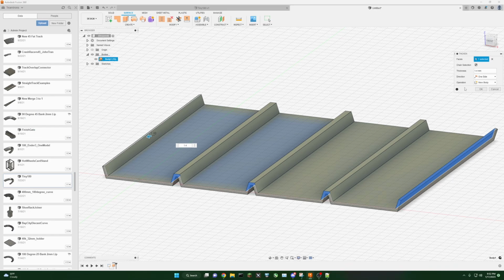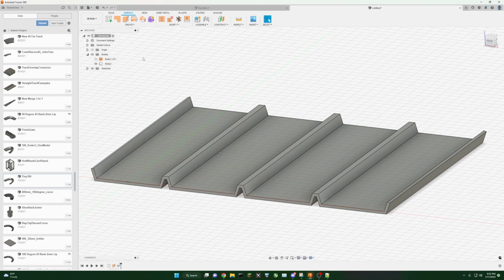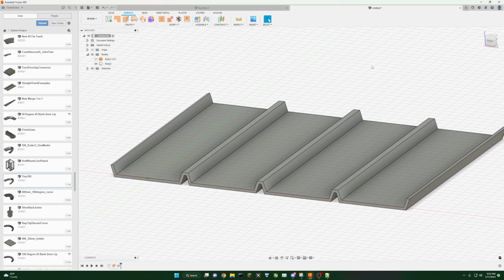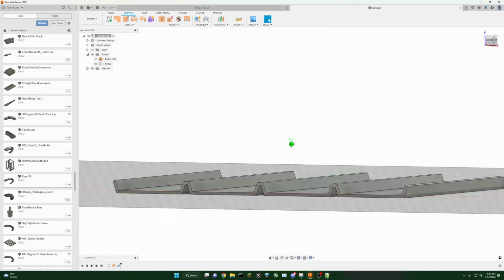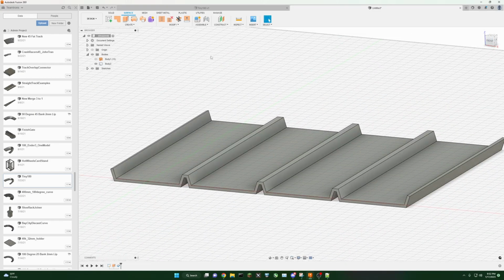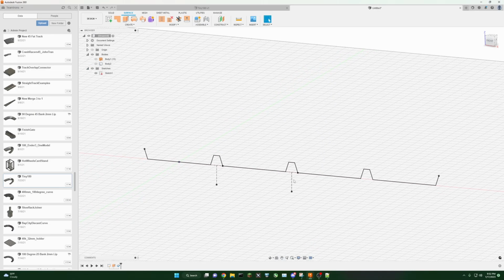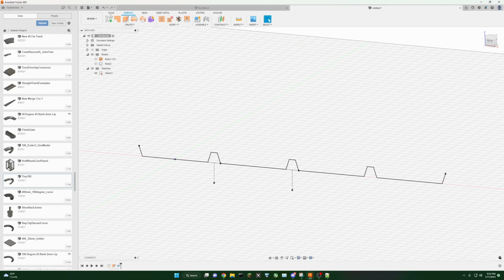And so now our body is 1.4 millimeters thick. And you notice a different icon here. So we have our original mesh body, and now we have a solid body. So this is solid. We can 3D print this. This is good.